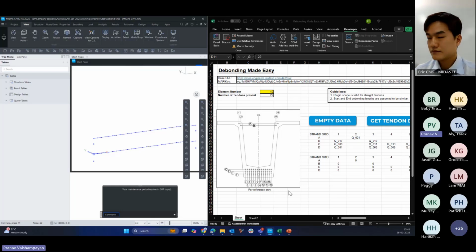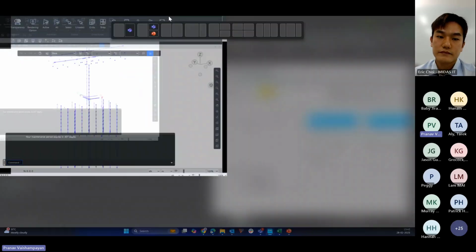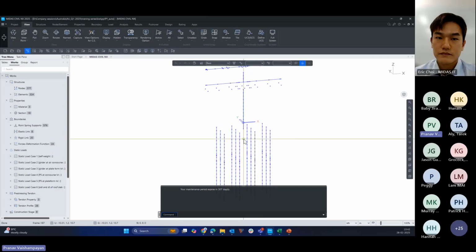The only point here is your PY curves should be the same at the respective depths. So even in this scenario, if I have selected a reference node as this node, just hypothetically, and I'm trying to generate piles from these nodes, until this point there would be no force deformation functions, but starting from this reference node, force deformation functions would be assigned at that particular location.